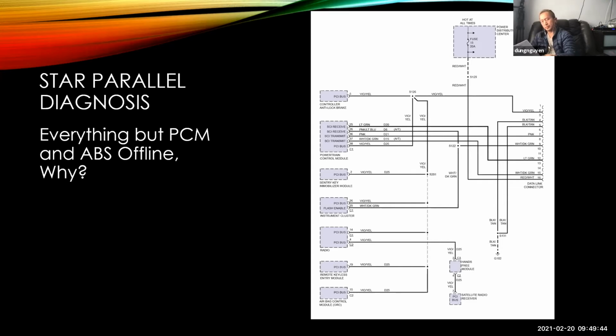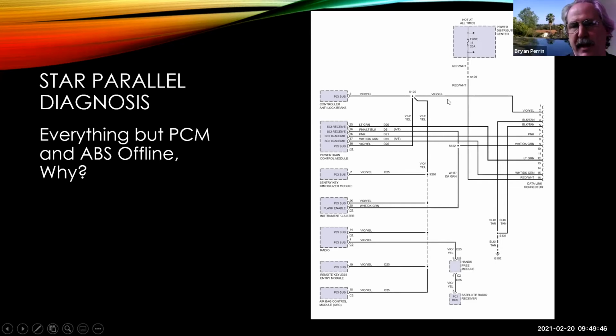Sorry. No worries. If I'm not being clear, always back me up. So that's why we're looking at this wire between these two. These are two good test points. Then go down the rabbit hole. Once I prove this is wrong, now I can get the labor to cut open a harness, trace a wire, or run another wire, whatever I need to do.